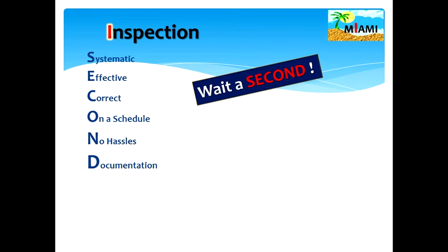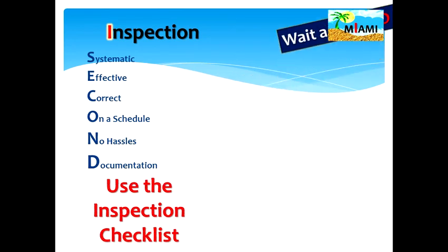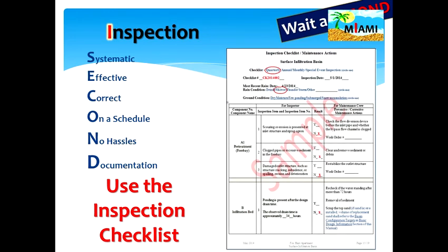All of these considerations can be addressed by using an inspection checklist, which lists the items to be inspected, tells us how to check, and provides a space to record the problems plus other important information, such as the weather on the day of the inspection, who was present, etc. It is worth noting that each type of BMP may have different items to check. An obvious example is that inspections of a wet pond will differ greatly from those of a sand filter. NJDEP has developed an inspection checklist for each of the commonly used BMPs. We will talk about them later.